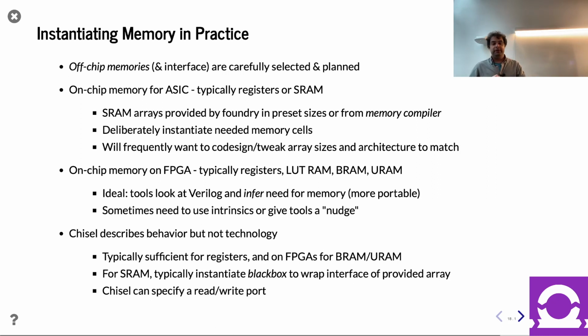One detail I want to point out: in Chisel, we mentioned there are two ways to declare ports. You can have ports that are implicit, where you declare memory and later on you either read or write it. Or you can say that memory dot read, that memory dot write, or you can even have a read/write port. Sometimes, if you're not careful with the way you express your Chisel, you can have a design such that in one place you're reading, and in another place you're writing, and as an architect you know you're never going to simultaneously read and write. That may not be obvious to the tools.